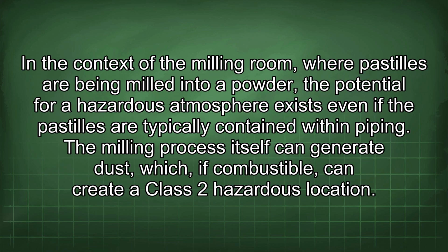In the context of the milling room, where pastils are being milled into a powder, the potential for a hazardous atmosphere exists even if the pastils are typically contained within piping. The milling process itself can generate dust, which, if combustible, can create a Class 2 hazardous location.